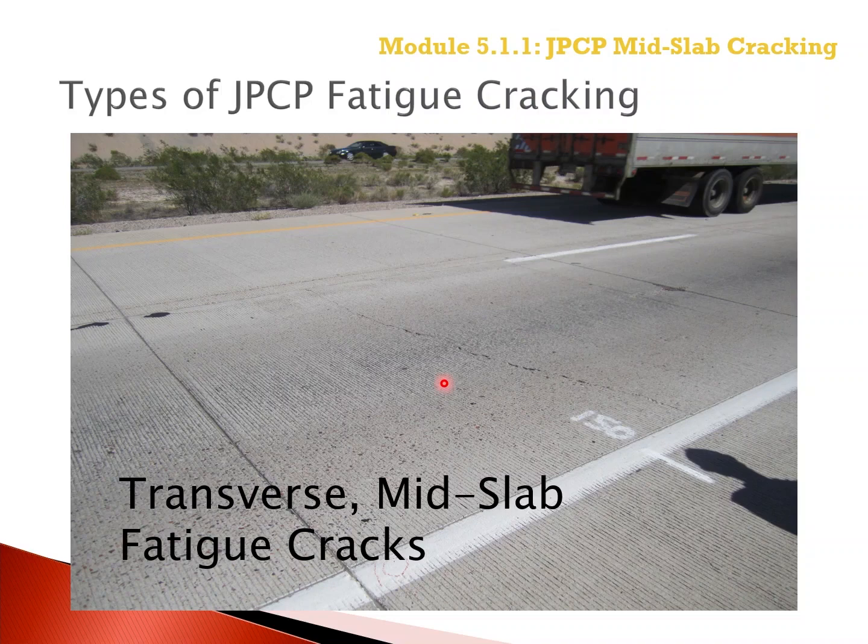The number of cracks in a slab does not matter or impact the percentage of cracked slabs. So one transverse crack across the width of the slab means the slab is cracked. If there are 2 transverse cracks across the slab, that still implies 1 cracked slab.